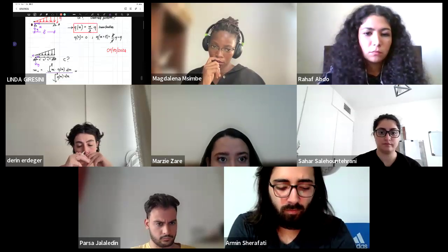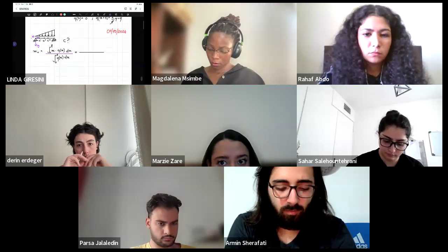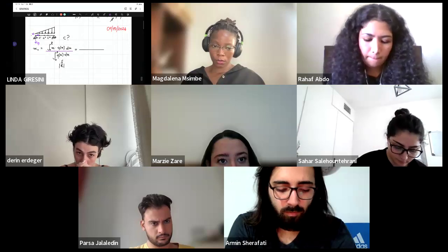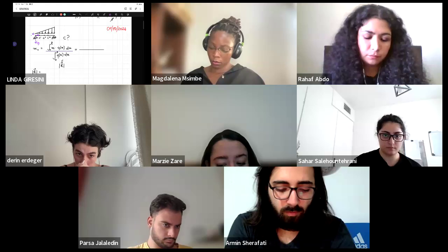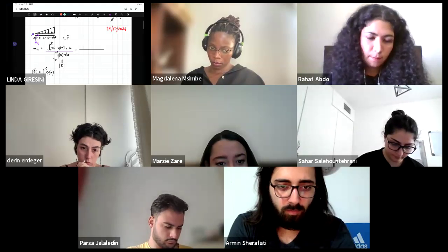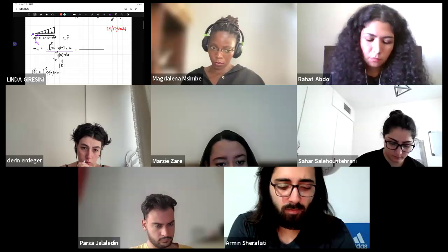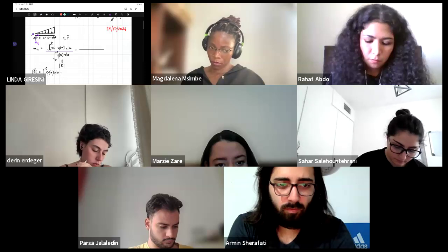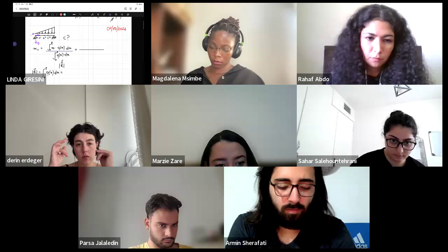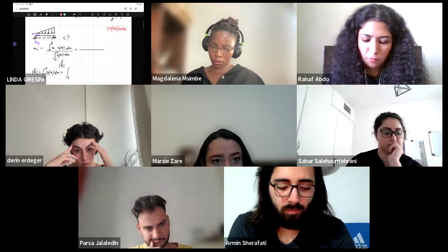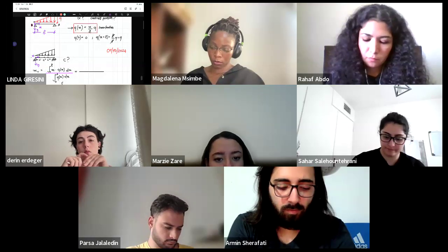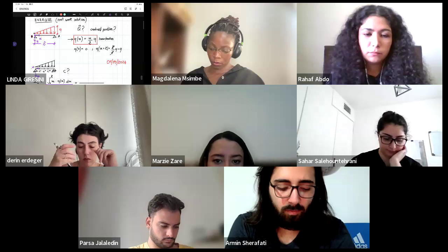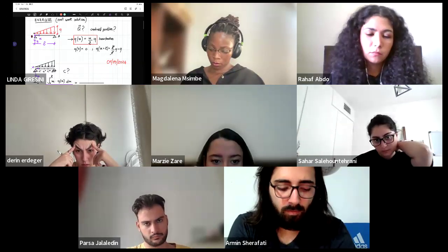So now we can solve this integral. First of all, let's solve this one, the resultant, the denominator. The resultant will be the integral from 0 to L of qx dx, equal to, I've just copied the previous expression, the denominator. So qx, as you remember, I told you last week, was expressed as x divided by L times q. Because for x equal to 0, 0 is the load, and for x equal to L, q is the load.